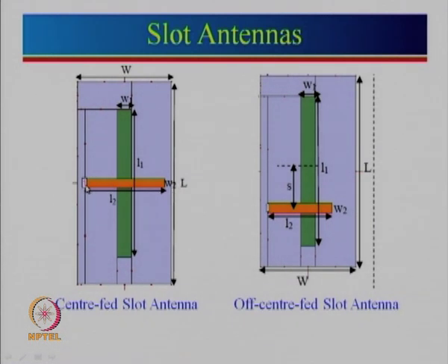So what is a microstrip line? Actually speaking, it is a line which is printed on, let's say, a PCB, a printed circuit board. On one side we have a ground plane with this particular slot, and on the other side we put this feed, and here we are feeding the antenna. The current flows through here and actually sees an open circuit.